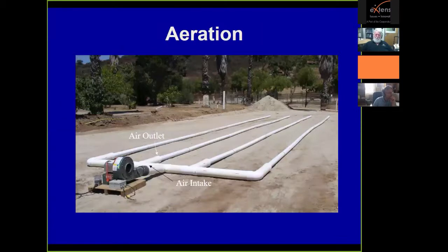This is how the aeration piping is laid out. Here we have a positive aeration system. We see the opening here on the side of the fan is the suction side. This is the discharge side of the fan. This transitions into a manifold, which is used to distribute the air through the distribution piping. Some composters will take another piece of aeration manifold and put it down at this far end over here and basically create a closed loop system.